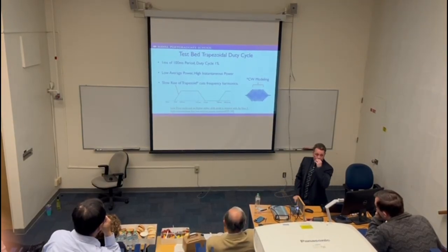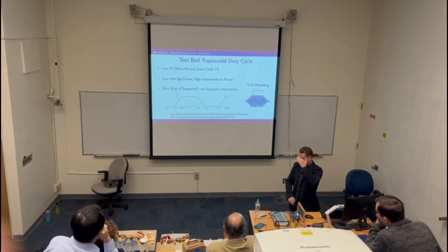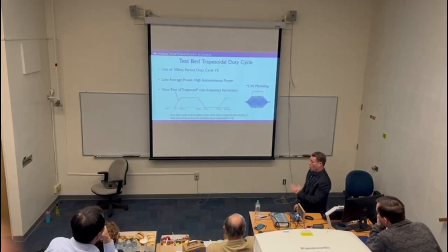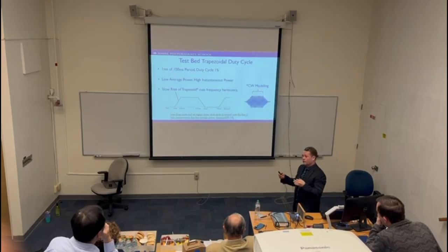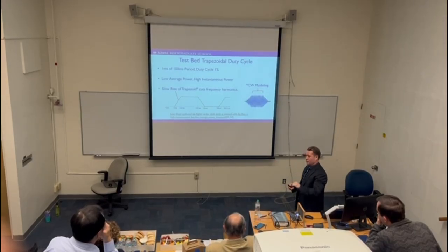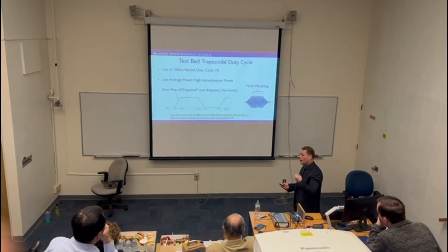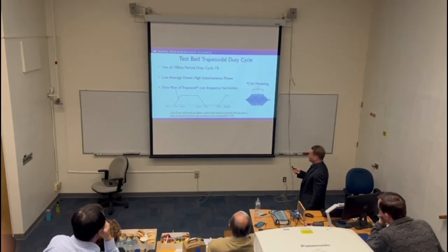Everybody knows in your DSP classes, if you have a fast rising square wave or a quick edge, it's going to have many high frequency components in the frequency domain, right? Well, if I take that slope, I can cut down on higher order harmonics. So then what I'm injecting is exactly the frequency that I want to inject, not higher order harmonics I wasn't intending, and I know what to attribute to what. So it's, again, kind of twofold.